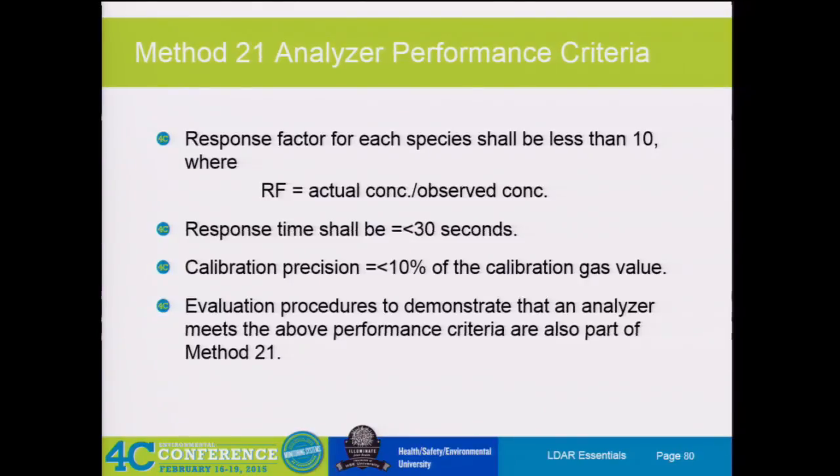Yeah. And so it absorbs the hydrocarbons also, which can throw off the results. Another one, and this is kind of off topic with where we're at, but another one to make sure when you're talking with your technicians is make sure that they check the tubing on their probes that are going into the analyzer. We actually were out doing an audit just a couple weeks ago, and this young gentleman could not come anywhere close to the readings that we were getting.